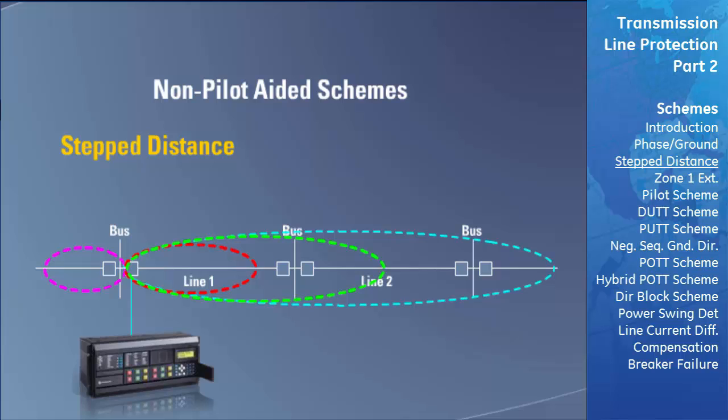However, the breaker on both ends of the transmission line must be opened to completely clear a fault. Therefore, another distance relay must be located on the right end of the transmission line to control that breaker. The relay on the right needs to be programmed with the same characteristics as the relay on the left. However, this one will be set up to be protecting in the opposite direction. Now, the zones of protection of each relay will detect any faults that occur on our protected transmission line. These relays will then proceed to open the breaker and clear the fault from their own respective end of the line.